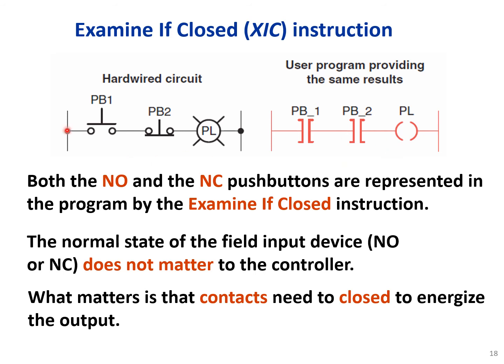So if we program this basically hardwired circuit like this, then the push button one, the first contact, this one, normally will be false, and the second one normally will be closed. Okay. So this one is normally closed. So this one is always true if we don't push this push button.